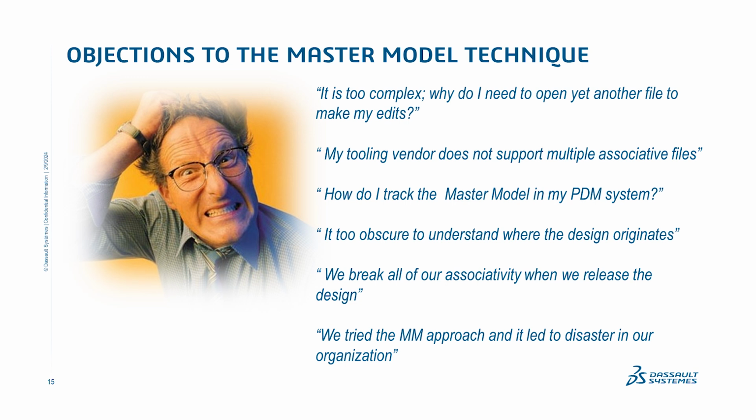The other thing too, kind of goes with the first point, is that it just becomes pretty obscure when you have a part and you see a stock feature in it. You're not sure where that is, how it drives the part, it becomes a little obscure. This is especially a problem when you have multiple derived parts on each other, and I'll talk about that and not to do that.